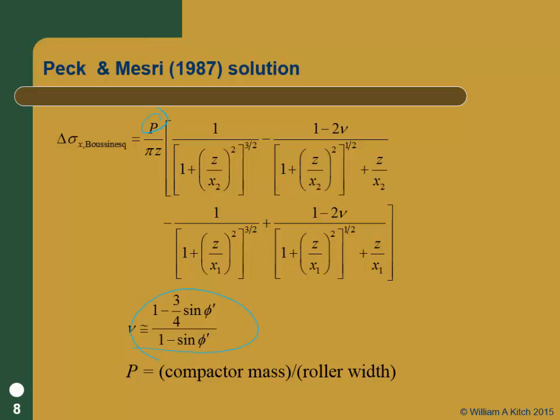And has anybody seen a wall compacted recently with these remote-controlled compactors? And they're small, right? About the size of this desk. Yeah, the last time I saw a wall constructed, the guy was out there, 30 feet from the wall with his little joysticks, driving the little compaction device back and forth behind the wall, and things no bigger than this desk. That's a really nice solution. You used to see a lot of people using pan vibrators to compact behind walls because the vibration gives a real nice density without a lot of stress. But now I think I've seen this more. Well, I don't know if I've seen it more often. Was it pretty common from what you've seen?